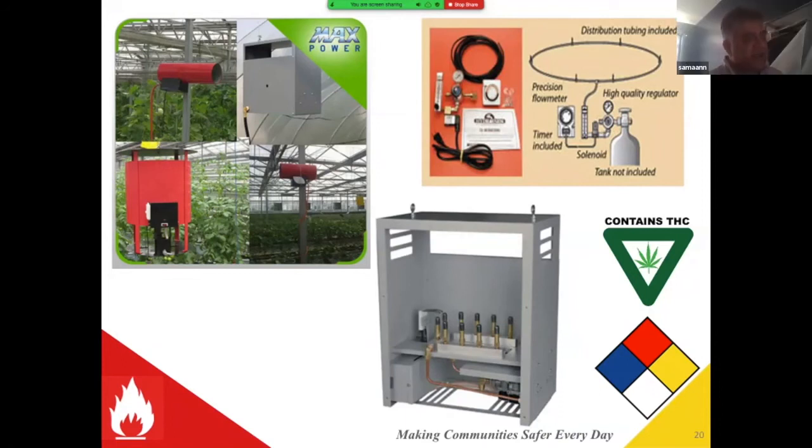Yeah, I do. It's in the IFGC, International Fuel Gas Code 2015, section 501.8. And it says that aggregate input ratings of unvented appliances that do not exceed 20 BTUs per cubic foot are allowed to be installed directly in the room. Okay, and I'd like to add that it is assumed that you would have normal ventilation rates in that space.